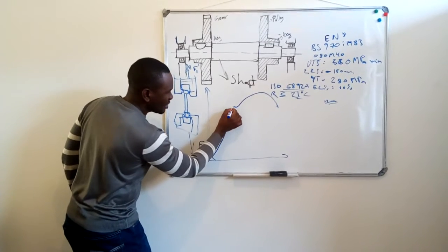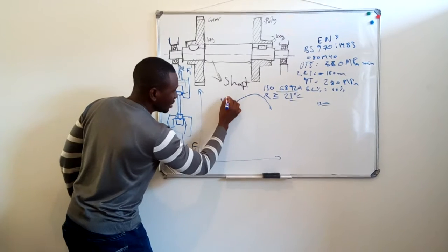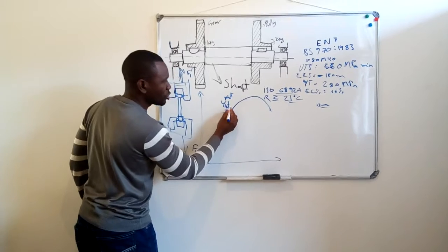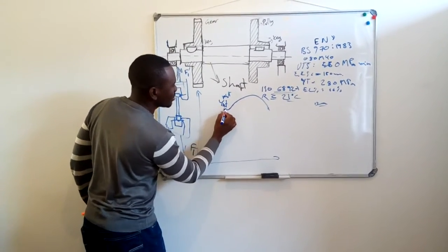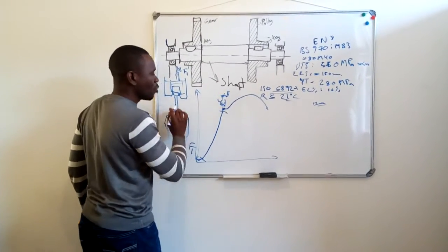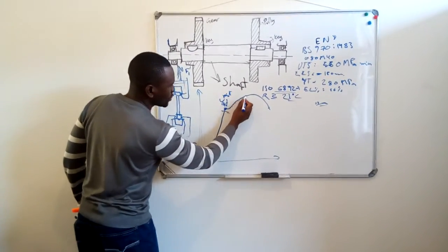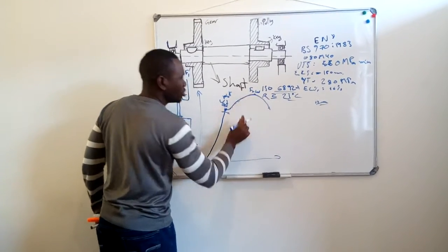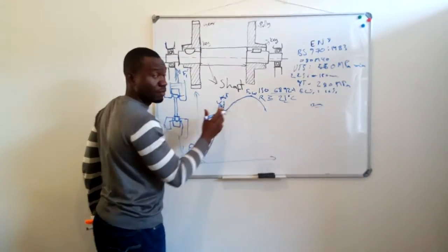Once it has reached the yield point, this is the turning point to the zone of plastic deformation. Once it has reached that spot, even if you stop the machine, the sample won't be able to return to its original sizes or dimensions. Then it goes on, and that's what we call the maximum load. This is the highest force that this material can withstand before it breaks.